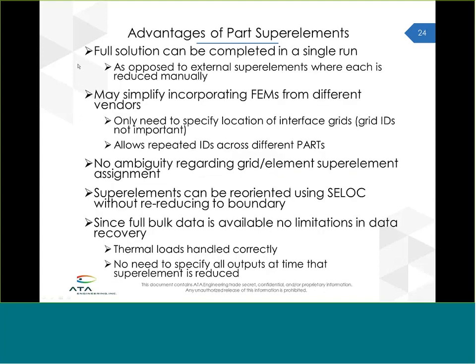So some of the advantages of part superelements is that really what part superelements does is it streamlines the process of creating several external superelements and then attaching them all together. So that's really the main benefit, is that you can complete a system level run all at once without having to stop, create an external superelement, and attach that in together. Certainly it can help attaching FEMs from different vendors. Maybe they used overlapping number IDs and you don't want to have to deal with renumbering. And all you really got to worry about is where are the interface grids located, just the location of those, not the IDs.